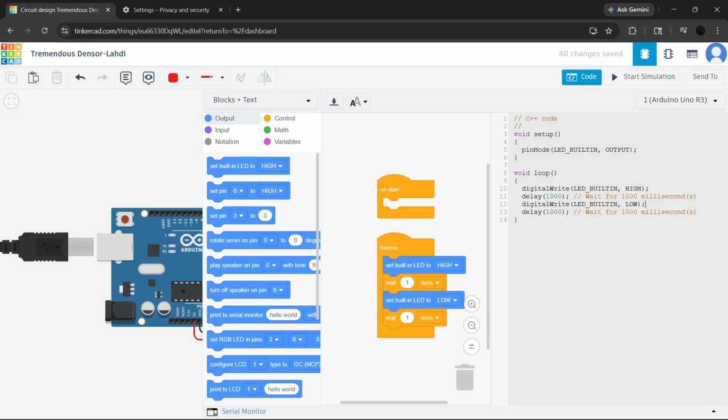Also pay close attention to your loops. If you have a while loop or a for loop running without any delay, the simulation may freeze because it is trying to process instructions too fast. In many cases, adding a small delay helps the simulator breathe and continue running normally. So if you've written a loop, make sure it includes a delay where appropriate. Think of it this way, if the microcontroller's brain gets stuck trying to process the first line of code endlessly, the whole circuit can fail before it even begins.